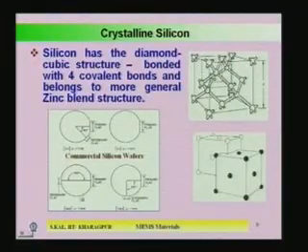110 direction. So, here are some figures you can see. Here you can see they cut here, this is known as a primary flat. Okay. This is a circular wafer. So, here is a flat which is known as the primary flat, and here is another flat which is known as the secondary flat.